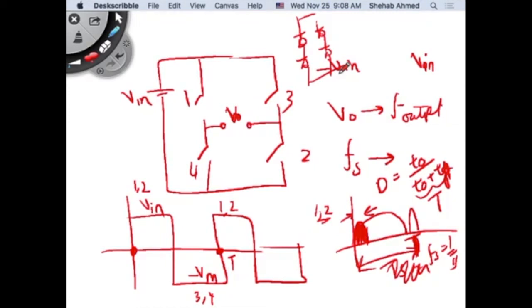If it's something different, a circuit that's intelligent enough to detect, okay, I have too much harmonic content, so I'm going to be just heating up my board without transferring a real amount of power to the system, right? Lots of current, lots of voltage harmonics, for example, or if this is a current waveform, lots of current harmonics with no power transfer. Then it's a different problem. Some equipment will tell you, we allow for voltage distortion of a certain amount. You exceed the voltage distortion, I will shut down. It's like the thermal shutdown we talked about the other day, right?